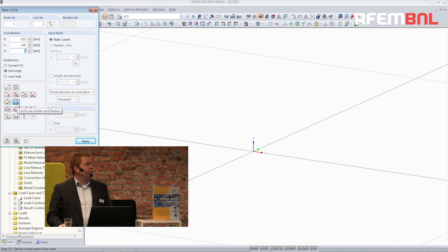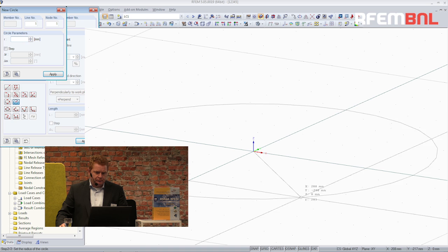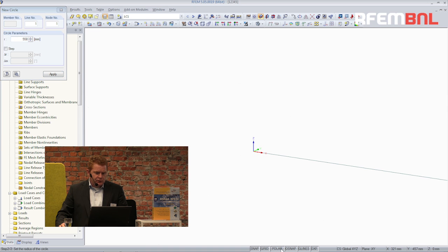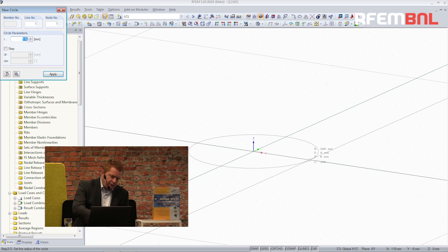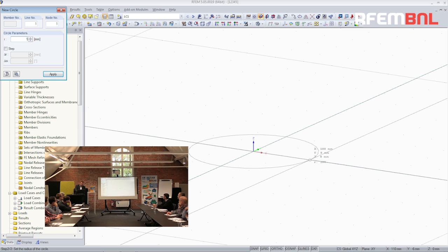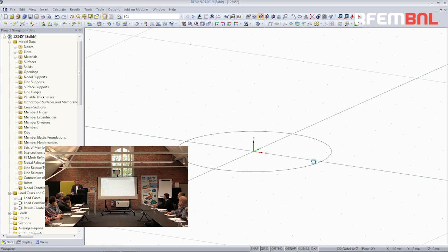I use this circle a lot in this presentation. So, circle, you know that I can change Cartesian to ortho. I will work in ortho in this way. And I will start with setting the radius, maybe it's 120 or something. Yeah, like this. So this is circle.